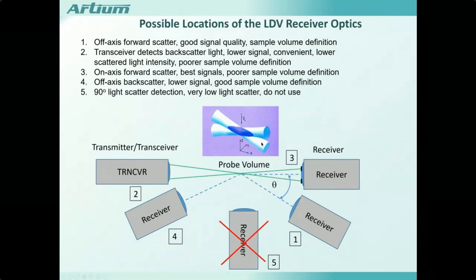When you have 2 beams focused and intersecting, you'll form an ellipsoidal volume. So where the beams fully overlap, you get complete interference. Where they are partially overlapped, you'll get a DC component, no interference. Not ideal, but you can make measurements with particles passing through that region. Generally, we like to define our measurements to just the region where the fringes are well defined and complete.